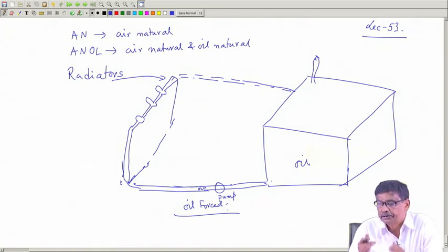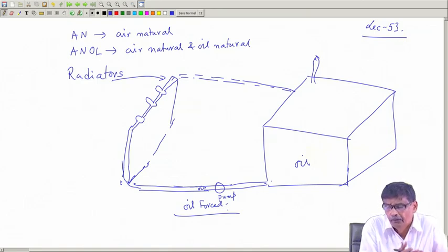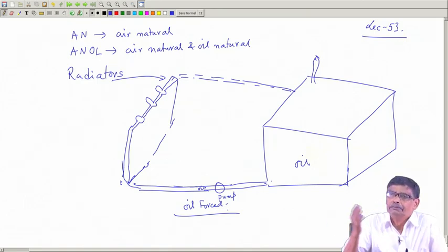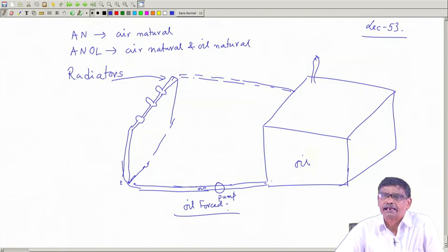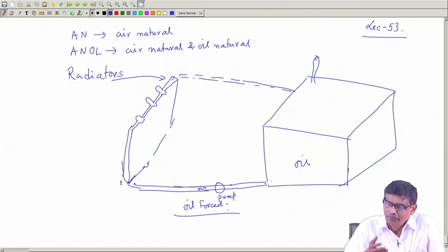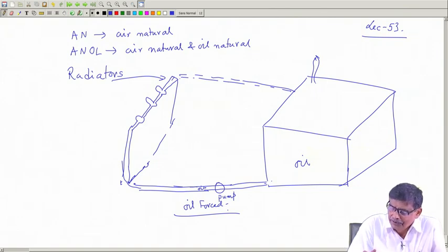So, the temperature rise of the transformer is within the limit, because whether it is very small or large transformers, the value of Bmax magnetic loading is approximately same, maybe 1.2 Weber per meter square. If you are using copper, almost delta is same, maybe 3 ampere per millimeter square. Those are fixed generally.